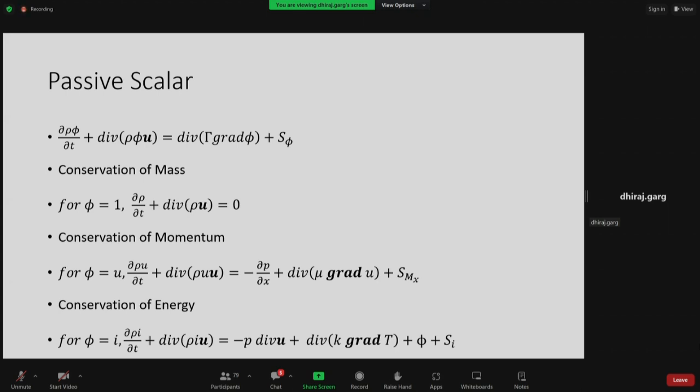If you take any control volume and look at a mass balance or population balance, anything entering the control volume, minus anything leaving, plus generation in the system, minus consumption in the system, is equal to the accumulation in the system.